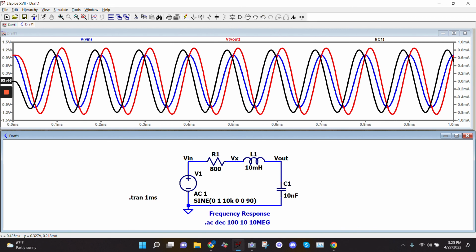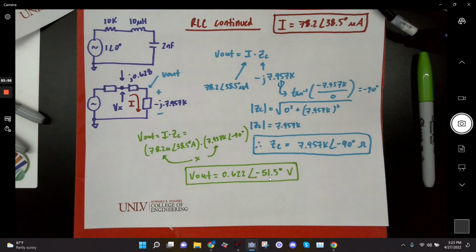What I was saying was, when you calculate the phase shift, and V out is equal to this voltage and then this phase shift, and then the current phase shift, will the difference between the current phase shift and the voltage phase shift always be 90, or can it change? Because in this case, the difference between the two of them is 90. The reason it worked out that way is because the inductor was contributing so little. Right. Okay. It won't always work out that way.